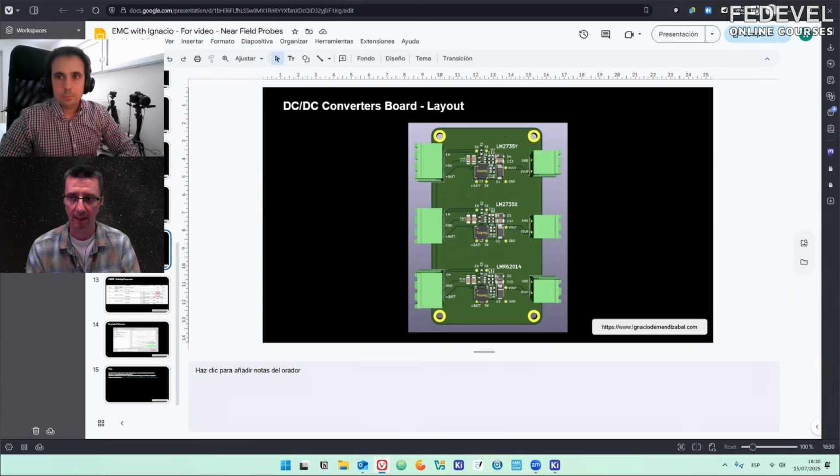Okay, so basically with these near field probe measurements, we can still find out if there may be a possible problem, and we may also find out if we fix something, it will disappear. That's how these near field measurements can help us, correct? Yes, that's correct. They are very good at giving you relative measurements.